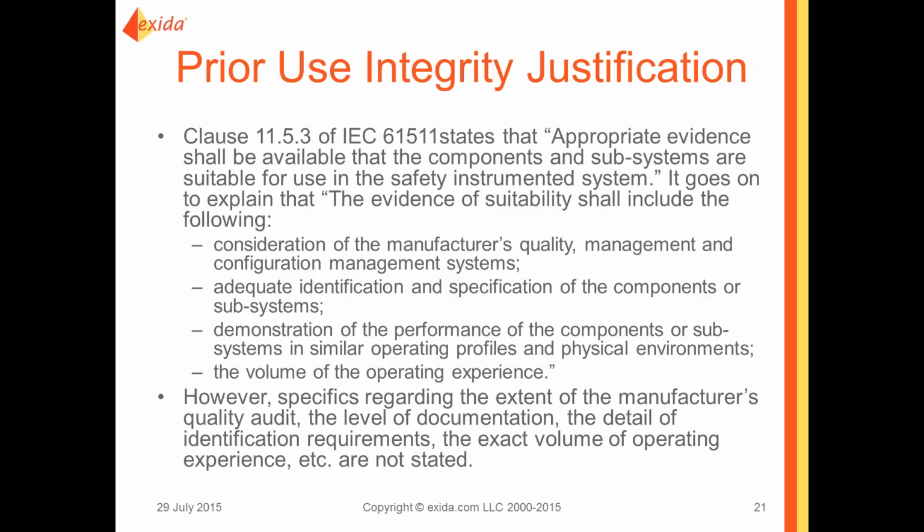accepting. So the standard says you need to look at manufacturer quality and management systems. You have to adequately identify and track the devices or systems. You have to demonstrate the performance of the components and subsystems in similar operating profiles, and you have to have a volume of operating experience. So whoever is using equipment based on proven in use, the end user ultimately has to review this and agree, and basically take the responsibility to say the devices are suitable for use in their safety systems.